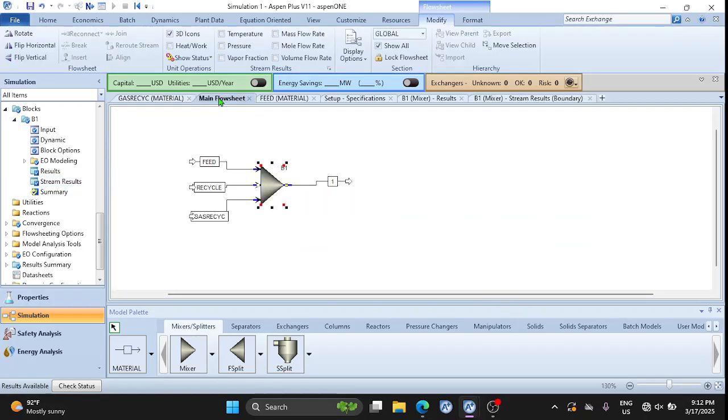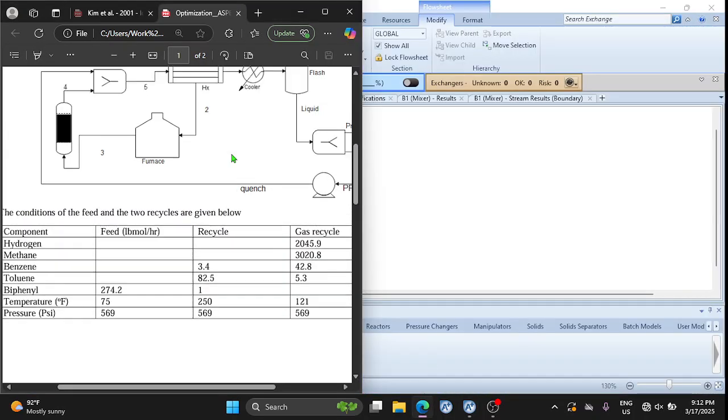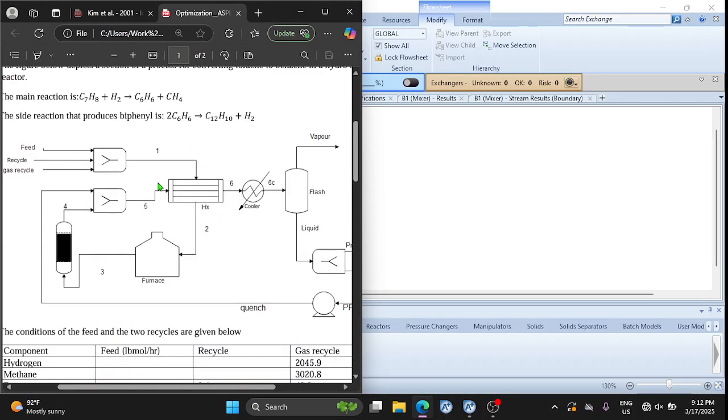Okay, now the next part, we are supposed to join this to a heat exchanger, and if you look at it critically, what comes out of the heat exchanger is going to a furnace, and then the output from the furnace is mixed with some other products and used. It's also going to pass to the heat exchanger. It means that whatever is going to come out of the furnace is definitely hotter than what came in. So if I'm going to use what came out to pass to the heat exchanger, then that is going to be the hot stream.